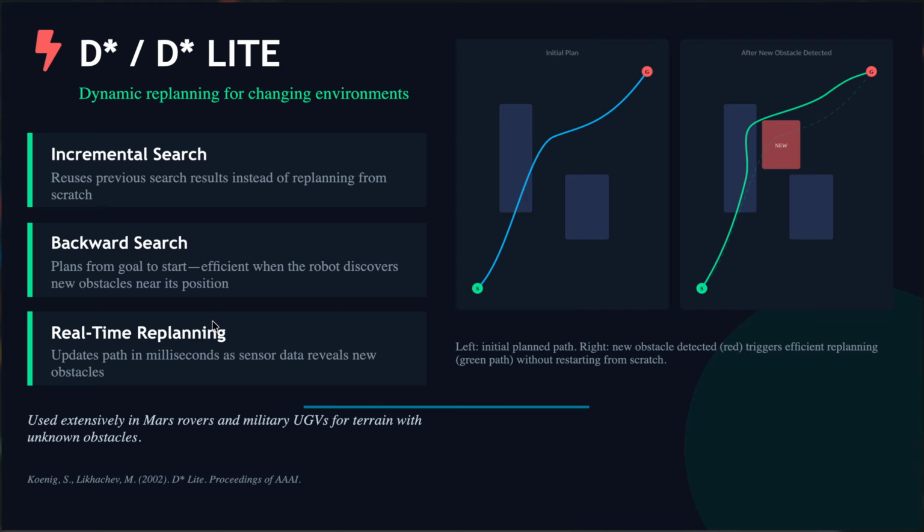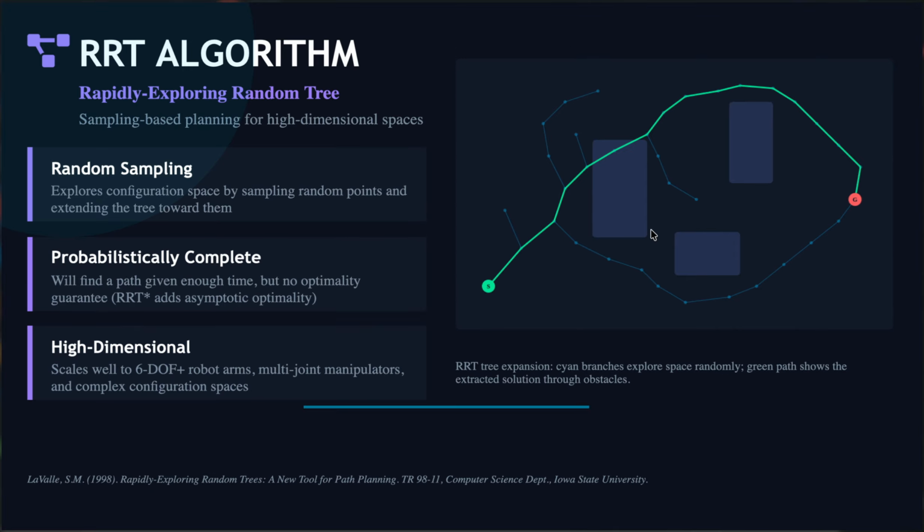And then there's real-time planning, which basically means if there is any obstacle in the path, all of a sudden it performs the search again, but instead of planning everything again, it just looks at the point that it's standing at and then tries to reconfigure the path to ensure that you avoid hitting anything. This is also the algorithm that's used in Tesla and other automated driving systems.